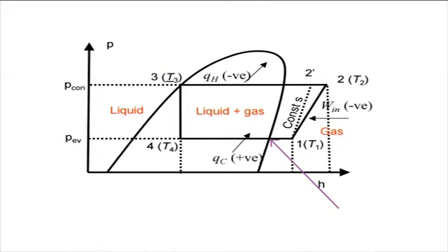PSI. The upside-down U figure shown on the diagram designates the points at which the refrigerant changes phase. The left vertical curve indicates the saturated liquid curve and the right vertical curve indicates the saturated vapor curve.